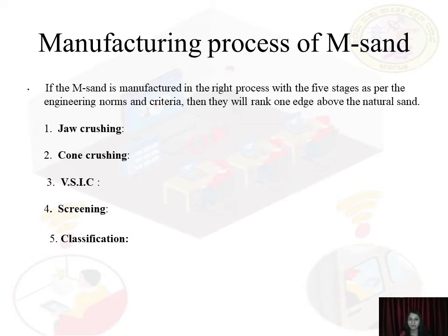And so what is the process of manufacturing sand? It usually commences from the quarrying of rocks, which involves blasting and drilling. The process produces rocks of smaller size, which are then transported to the crushing plants. And then the sand is usually produced in a three-stage crushing process. What are those three-stage crushing processes?